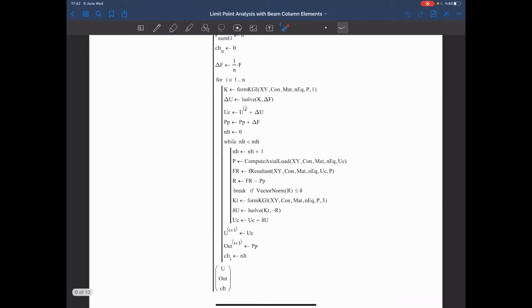Now we have, this is the incremental part, and here we have the iterations. For the increments, again, we first solve and determine the structural stiffness matrix. Remember, that's the flag. Flag gives me the elastic stiffness, and then I'm performing this linear solution and obtain the displacement increments, and then the iterations start,